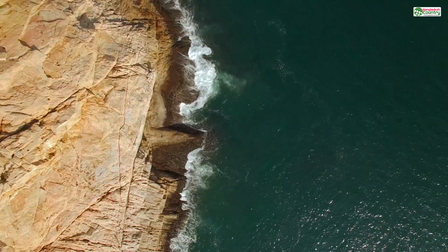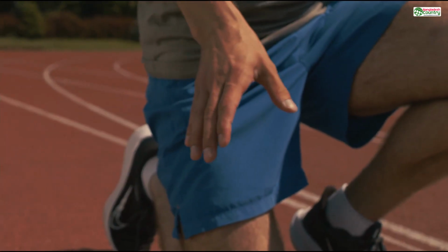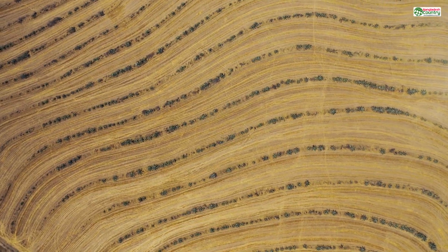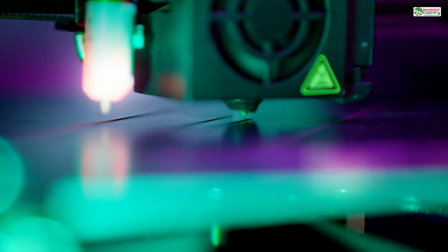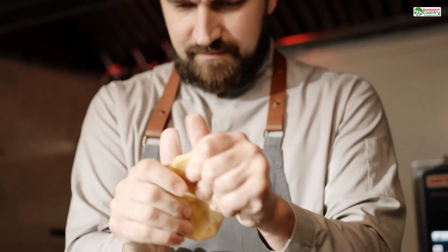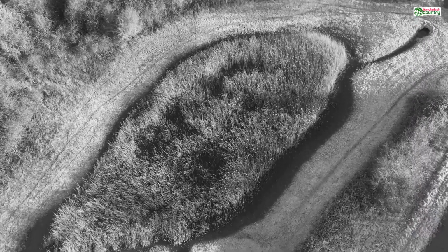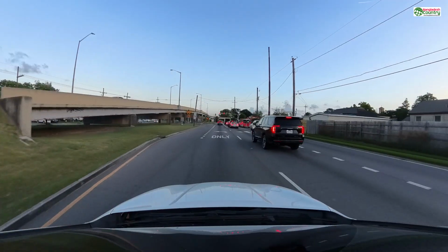Patterns like lines or zigzag are the fastest to print. The printer's nozzle can move in long, straight lines without having to change direction often. This makes them fantastic for early-stage prototypes where you just need to check the size and shape of a part quickly. The trade-off? They're only strong in one direction, perpendicular to the lines. They're weak to forces that run parallel to the printed lines.